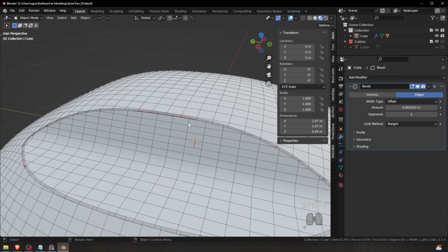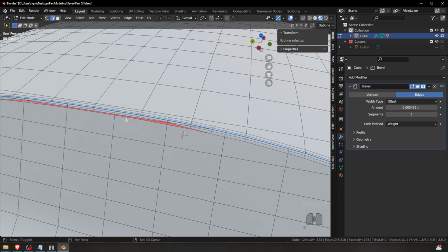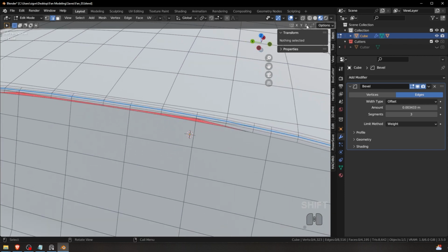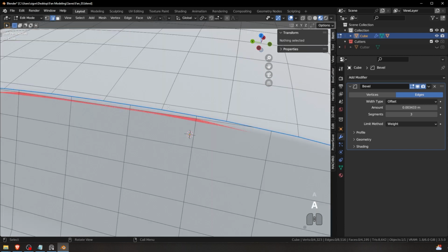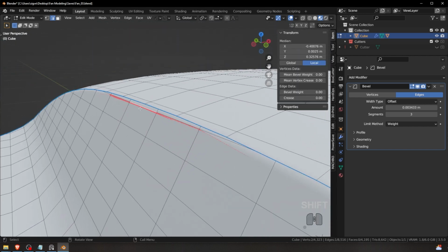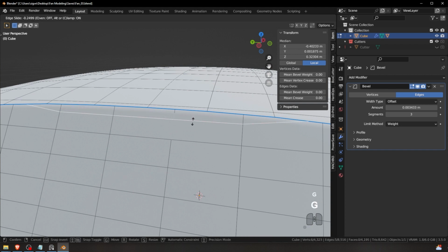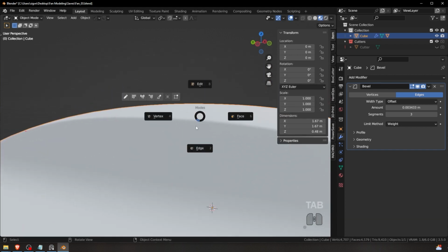It still doesn't work. So now go into edge mode, and what we are going to actually do is remove some edges. Let me go into object mode and quickly disable this wireframe in here. So what is happening right now is this edge is getting overlapped. If you move it here, it disappears. See?